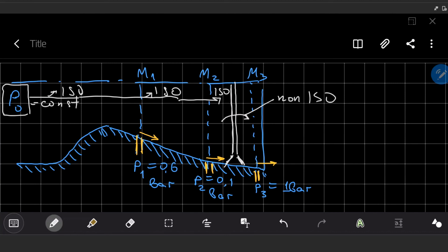Okay, and for the region of transition through the shock wave, flow will not be isentropic, but we know, using the second law of thermodynamics, how to calculate the pressure drop, the stagnation pressure drop. So we know that P0 at 3 divided by P0 at 2 is a function of Mach number. This function of Mach number exists in the book and is also presented inside Appendix B. Here, as a practical example, I will just use Appendix B, which is an exact representation of the formulas from the book.